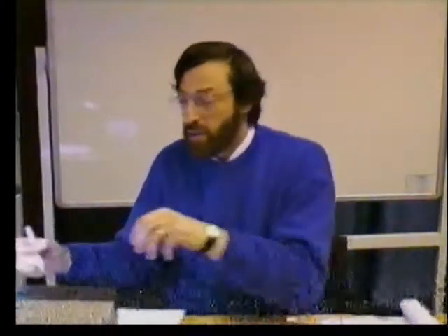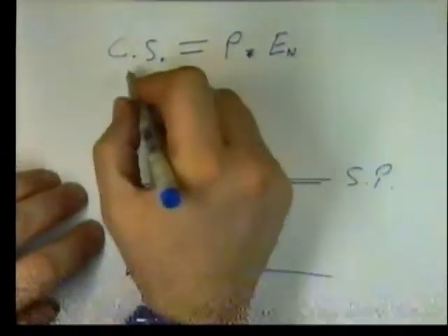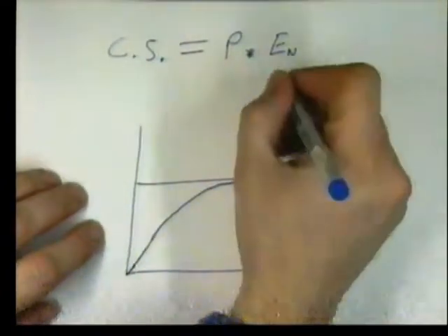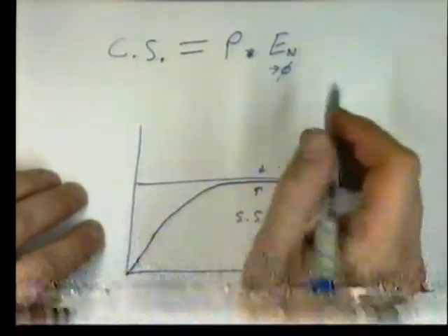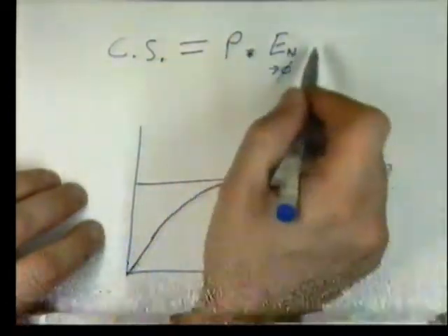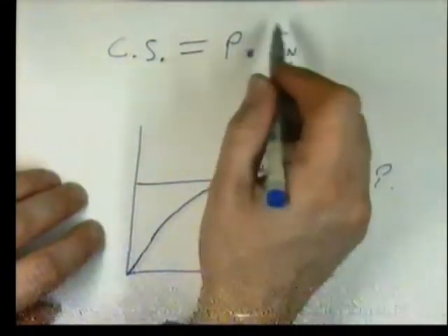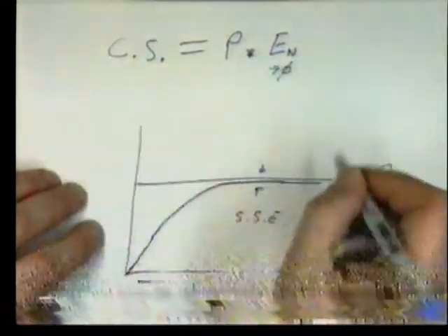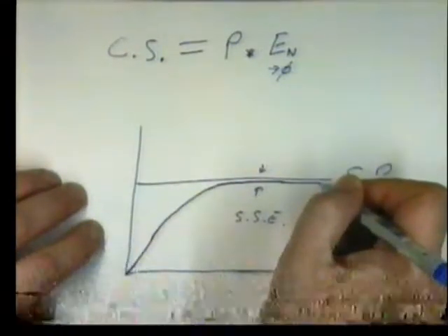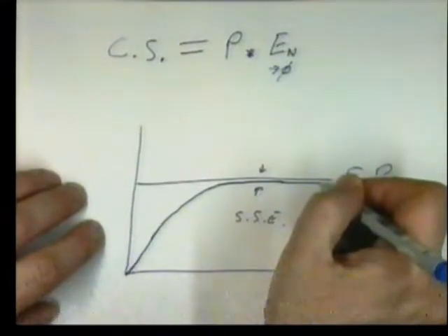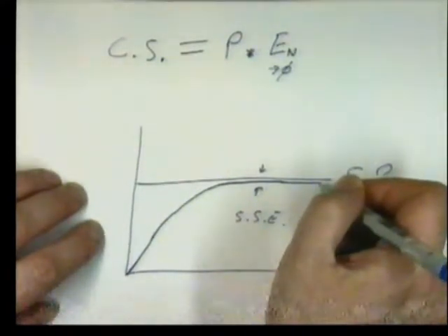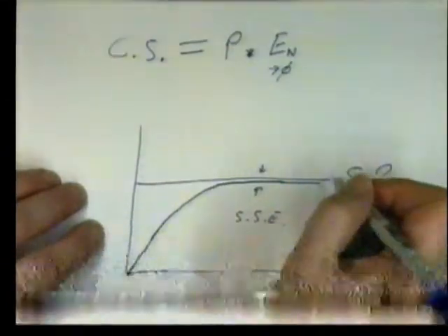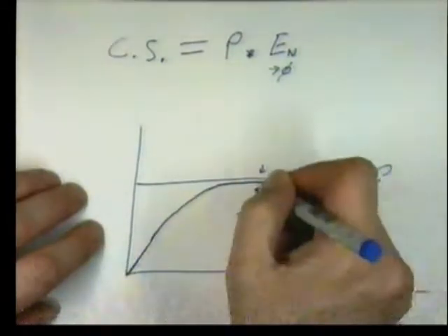Why is that? Well, look at the equation. If the control signal is proportional to the error, and here the error is tending to 0 at that point, then the contribution by the whole of the proportional term also is tending to 0, and it hardly has any effect at all on the control signal. In fact, what we've done, we've reached the steady state position whereby we've got our valve a little bit open, and that is equally matching the energy loss in the system, and so we just drift along just below or just above it. What we have to do is to accumulate these errors.